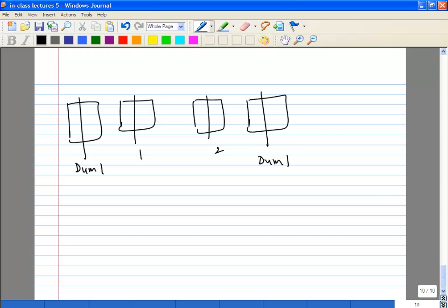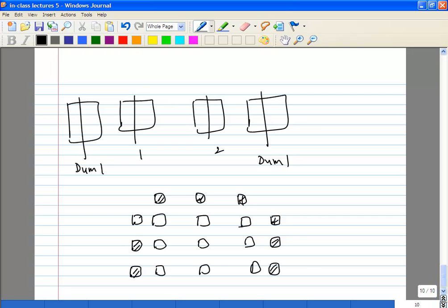And in reality, you want to have dummies in all directions. So let's say your transistor, in this case I have shown a very simple array, something like this. So your transistor is laid out in 9 sections. You probably want to have dummies in all directions. You want to have something like this such that it's protected on all sides, and ideally these dummies will be identical to your main transistor section. So every transistor in all directions will see the same number of devices and the same environment.